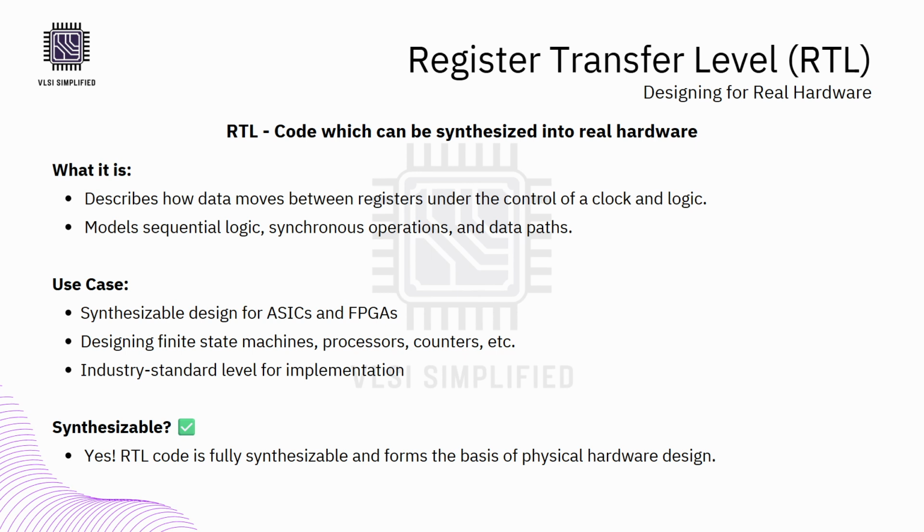You define what happens on the rising edge of a clock, how reset behaves, and how values are passed across logic. And the best part, RTL Verilog is fully synthesizable. Meaning it can be taken from your code, passed through a synthesis tool and turned into gate level hardware that can actually be fabricated. This is the level you will spend most of your time in as a front-end VLSI design engineer.